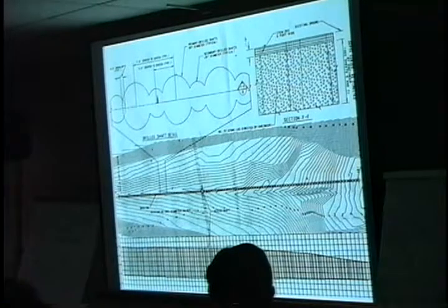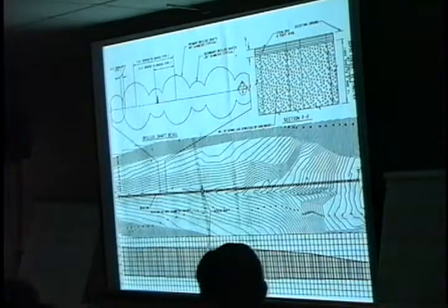One other option we were considering here, again this is a pretty complex situation, we don't deal with these all the time, but we were actually considering drilling caissons with further spacing, not necessarily side by side, and actually directional drill a tile or a drain system through those, connecting them to get the water out that way.